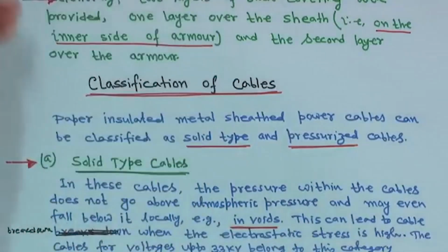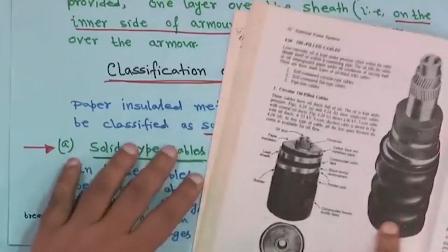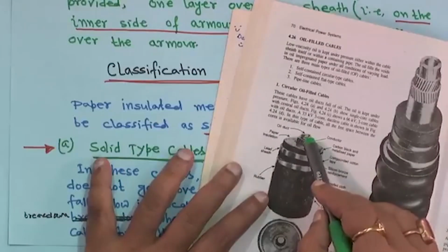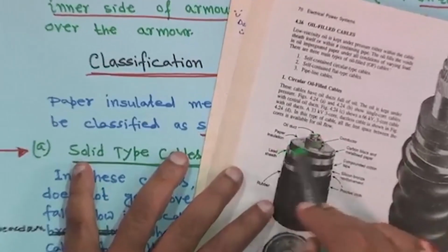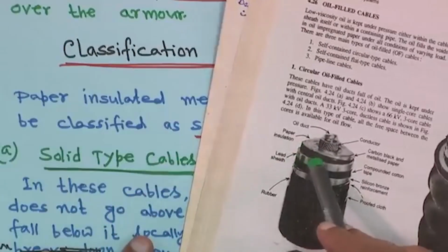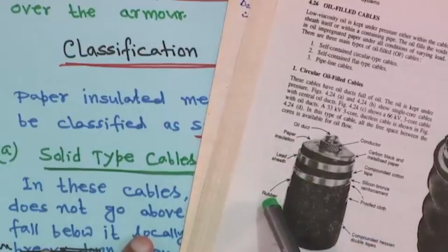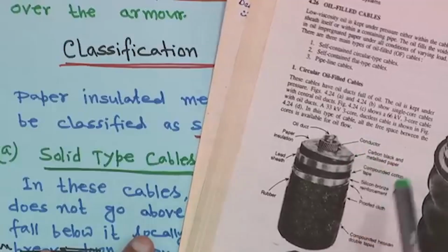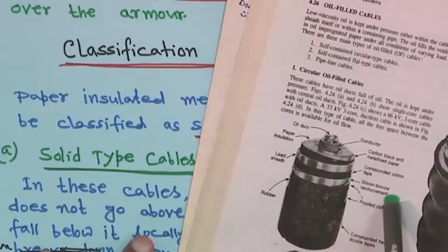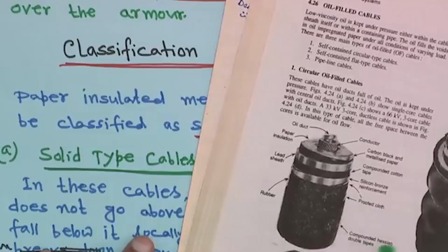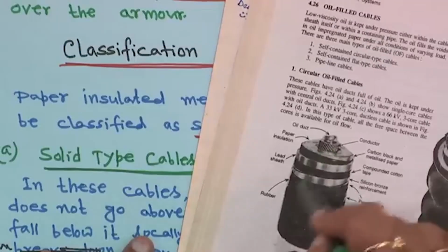So, if you look at this diagram, right. Of course, this is an oil duct cable, that does not matter, forget about that. Look, after this the paper insulation is there, over insulation lead sheath is there, and after that the rubber is also there, and this is the conductor. Here carbon black and metallized paper is also there, then compounded cotton tape, then silicon bronze reinforcement, and finally proofed cloth and compounded Hessian double tapes, right. Look, so many materials are there for the cable.